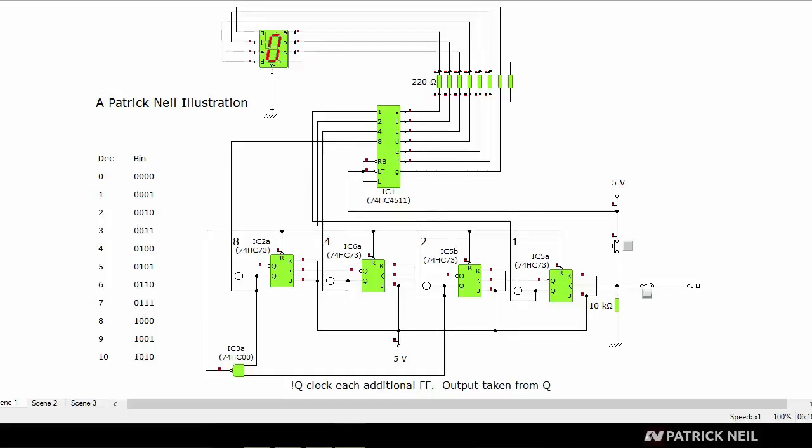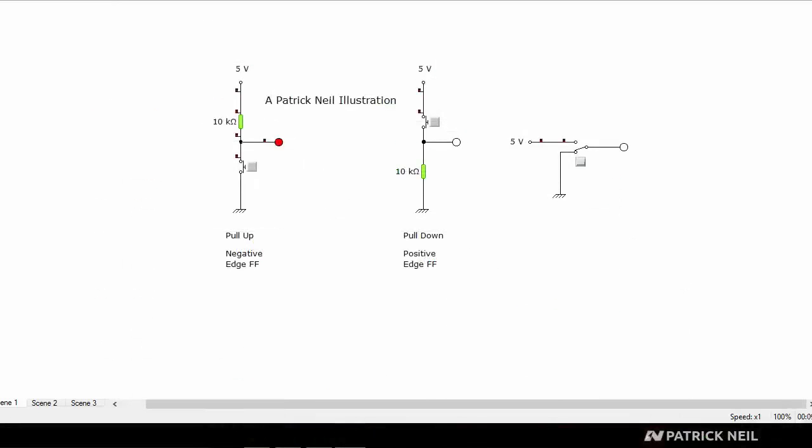To understand flip-flops, let's dig a little deeper into digital electronics. As you know, digital electronics operate in two discrete voltage levels, high and low. These are the signals necessary for a flip-flop to operate. So let us take a look and see how we will design a circuit that can produce a digital signal on its output. The circuit on my left is called a pull-up resistor, and the circuit on my right is called a pull-down resistor. These two circuits can be seen in all digital circuits.